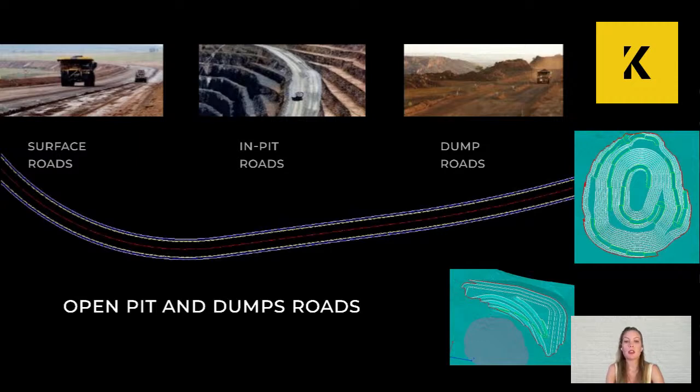So these roads need a strong rock base to handle heavy dump trucks, and protective barriers like windrows or visible stakes are often used to keep trucks on track.